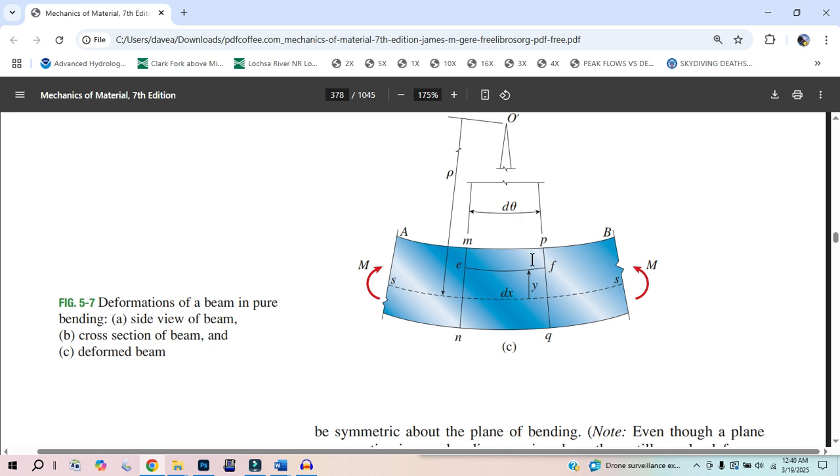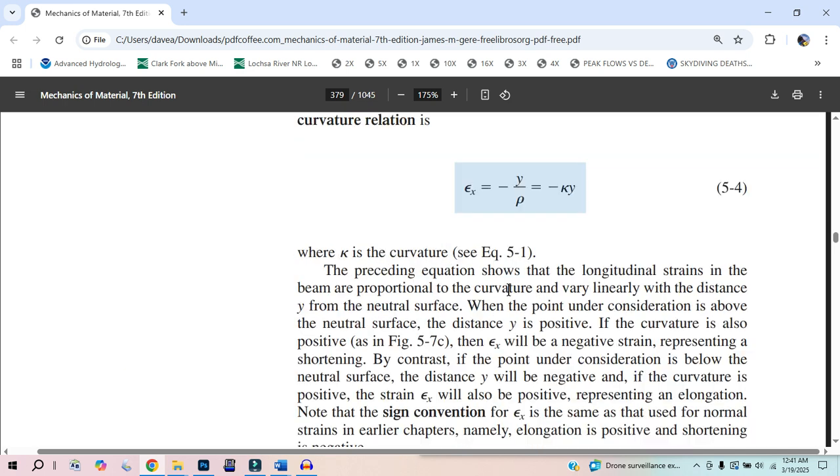And so if we take the equation, the length final minus length initial, the two L naughts are going to cancel, and we're just going to be left with minus y divided by rho L naught. That is the change in length: negative y divided by rho L naught. Strain is change in length divided by original length, so that L naught goes away, and you get strain is just negative y divided by rho.